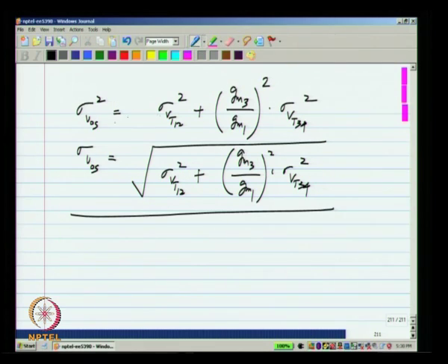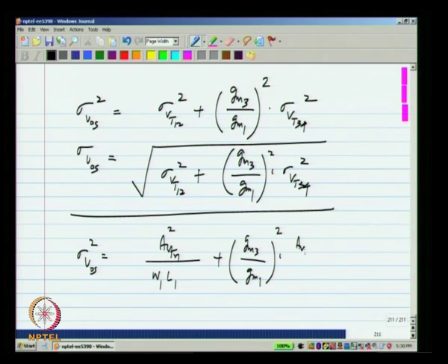And this can be further calculated from the process data. AVT square by W1 L1. By the way, this is the AVT of the NMOS transistors, which could be different from the AVT of the PMOS transistors.